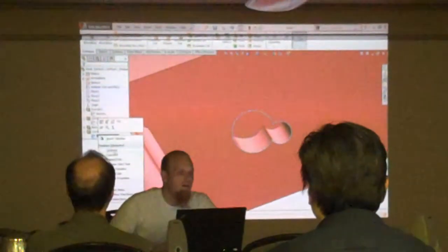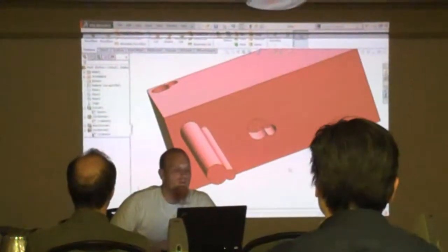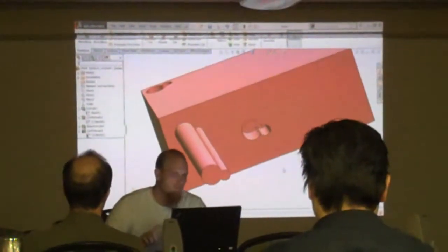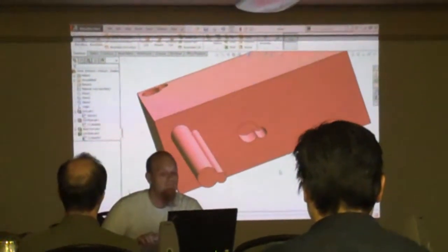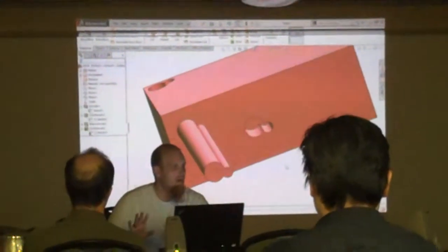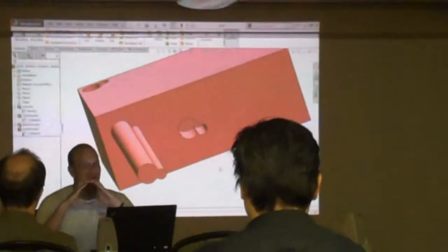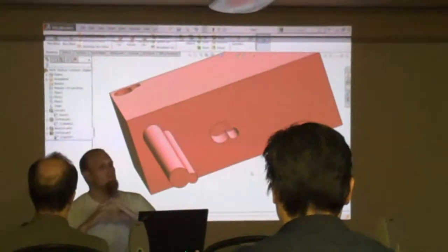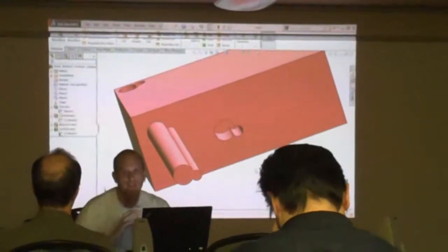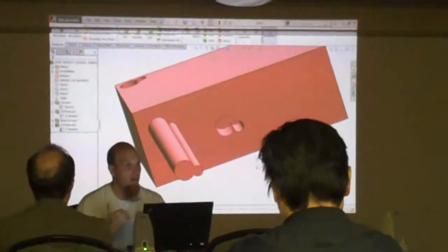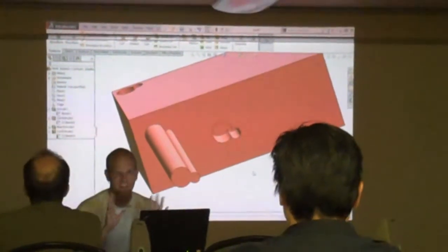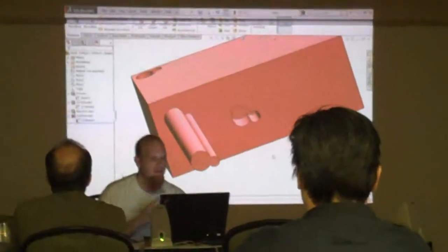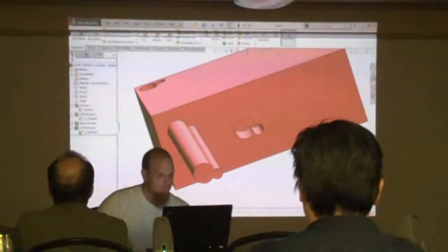All right. When you underive a sketch, any and all relationships that went with that particular sketch, dimensions, relations, all of them are gone. Even if it was something as simple as a square, the horizontals, verticals, perpendiculars, parallels, dimensions, whatever went with it are gone. It's just dumb geometry, like you copied and pasted from AutoCAD into a SolidWorks sketch. Okay? It's all there.